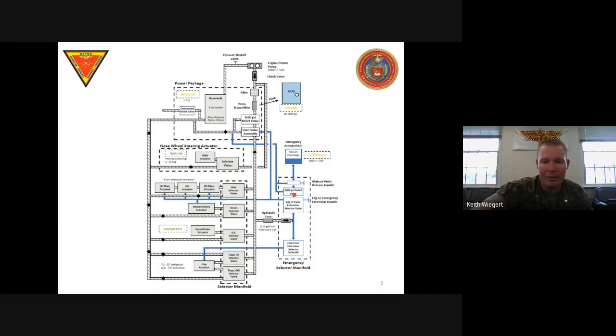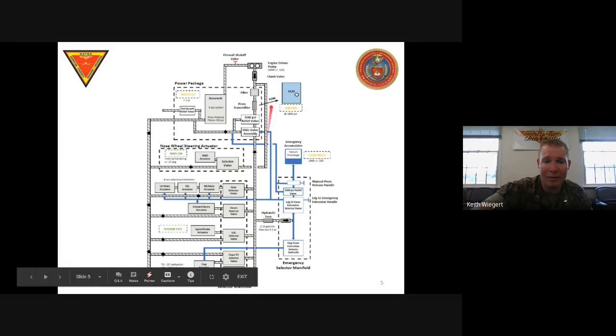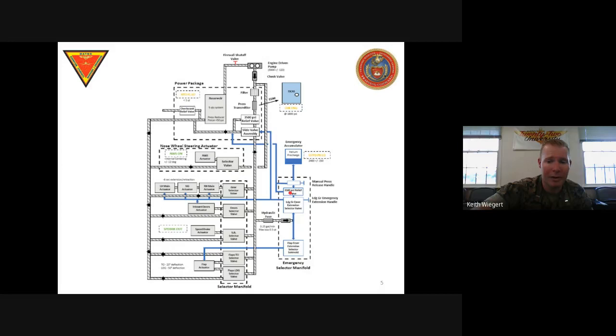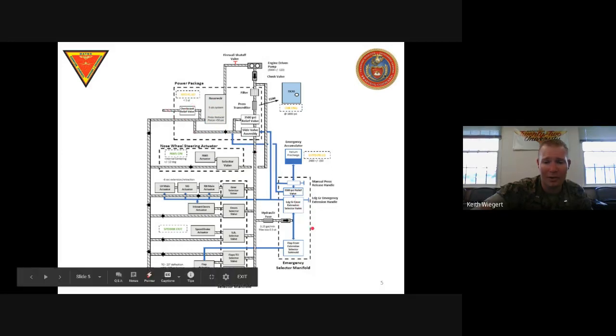And then we're going to go to the 3,000 psi relief valve. It does the same thing over here because we're going through a one-way check valve. So if this side is malfunctioning and producing greater than 3,000 psi or 3,500 psi, then so will this side. It still needs to relieve that pressure. So the 3,500 psi relief valve is going to send anything too high a pressure again back to the main side, so it can go to the reservoir or overboard to release that pressure.